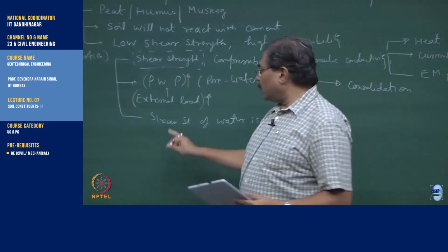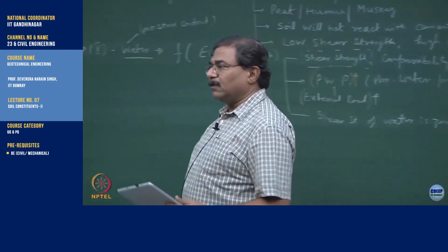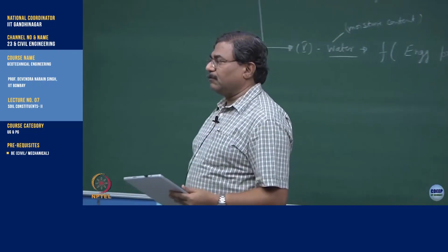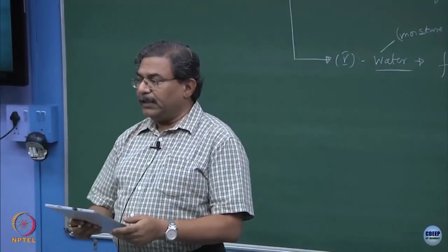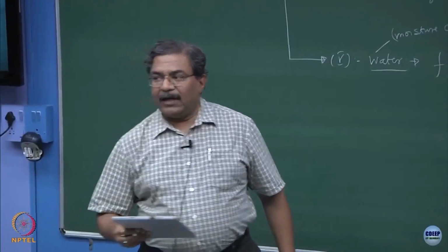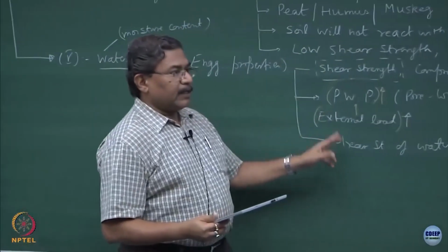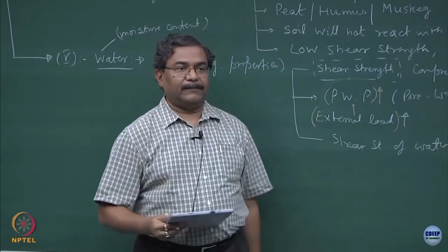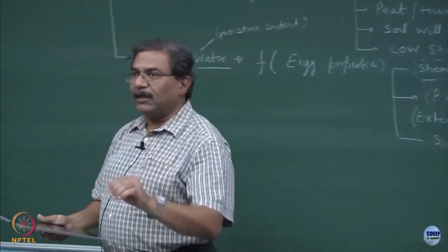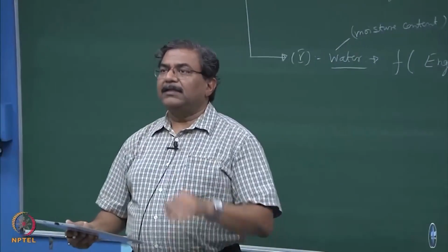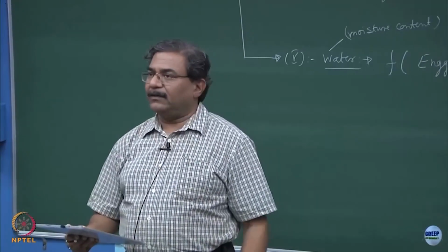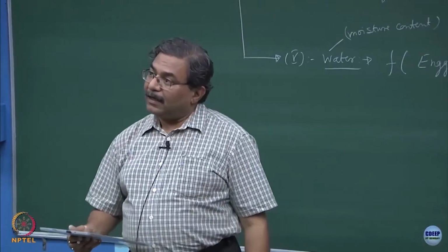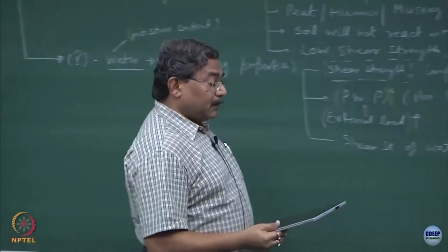The question is what water is doing. Water takes only compression or compressive loads. It cannot take any shear stresses. In fact, the more the moisture content, the more the water content, the shear strength is going to be absolutely less. That is the reason if you enter into a marshy deposit, chances are that you will sink, you can't walk. Clear? I gave you this analogy in the last lecture also.